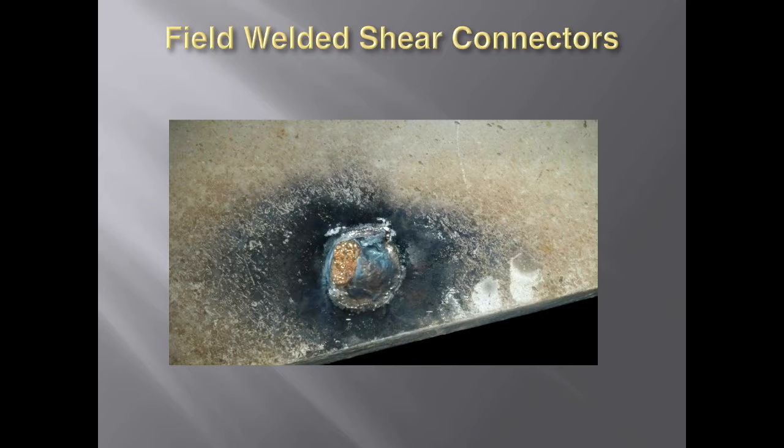So they ended up having to grind that out, and a welder had to come in and weld overhead to patch that and fix it. Of course, we had to go through the engineer of record to make sure everybody was okay with the fix, and then they also had to do a welding procedure, a repair procedure, and have that sent in and okayed.